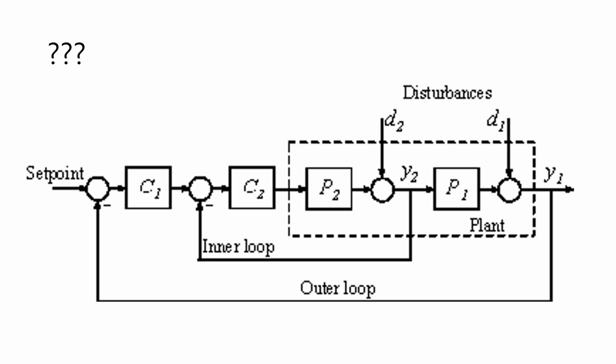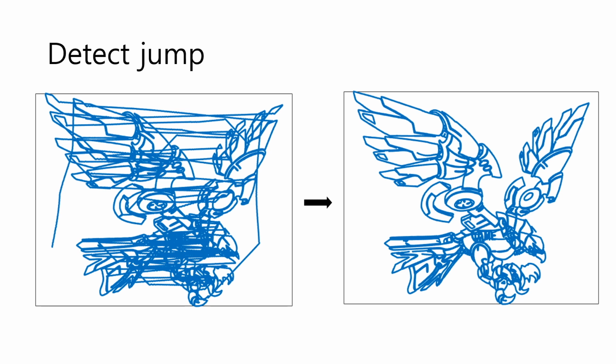We have also separated the sources of disturbances. Disturbance D2 in the image would be high frequency disturbances, such as disturbances arising from the DC motor, friction in the gears, etc. Disturbance D1 are relatively low frequency disturbances, mostly external disturbances, such as someone grabbing on the motor shaft. In order to separate the disturbances effectively, we would need to have the inner loop iterating at a much higher frequency than the outer loop, so that the inner closed loop system appears as a single block to the outer loop, as we had in the single PID control loop before. By setting the inner PID loop aggressively and the outer PID loop conservatively, we can improve the performance of our system.